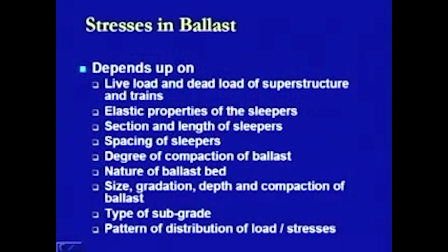The nature of the ballast bed means the type of material we are using in this ballast bed. On the basis of the type of material, it has a certain capability of taking the loads or the stresses. Further, in continuation, the specifications related to size, gradation, depth and compaction of the ballast also have their effect.